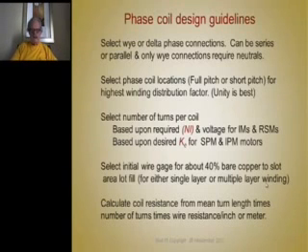As we progress along in the design of a machine, at some point you've selected whether you're going to use a wye or delta connection, or whether you're going to use series or parallel connections inside those wye and delta connections to adjust your number of turns. Let me point out that with permanent magnet machines, delta phase connections are very dangerous unless you're able to guarantee balanced phase windings. Otherwise you get circulating currents in the delta. I don't think I've mentioned that before. It's important to mention that.